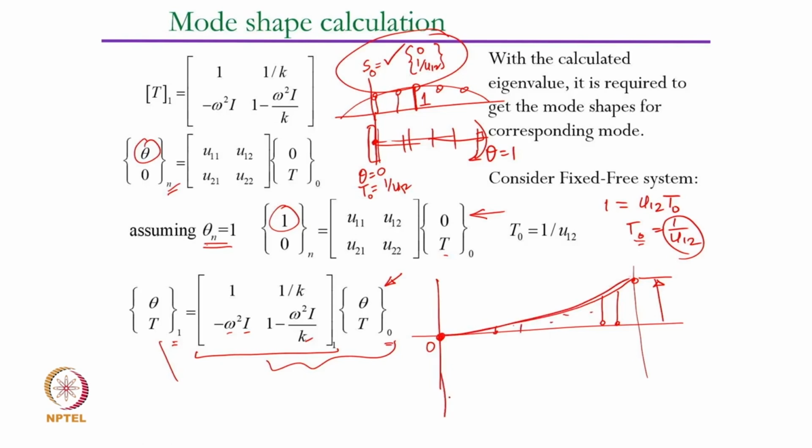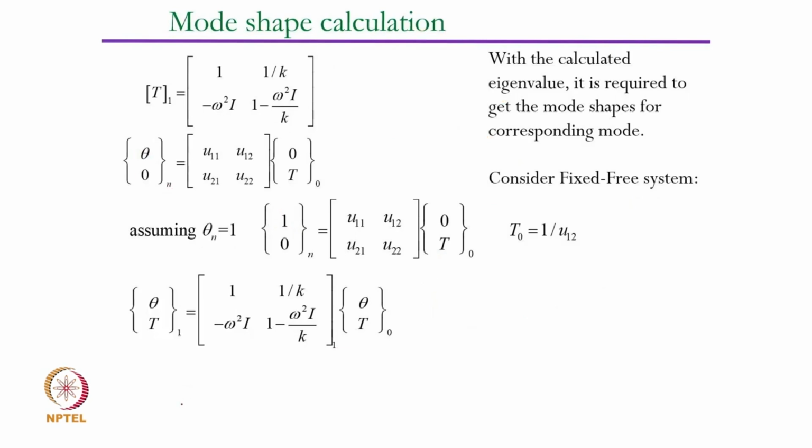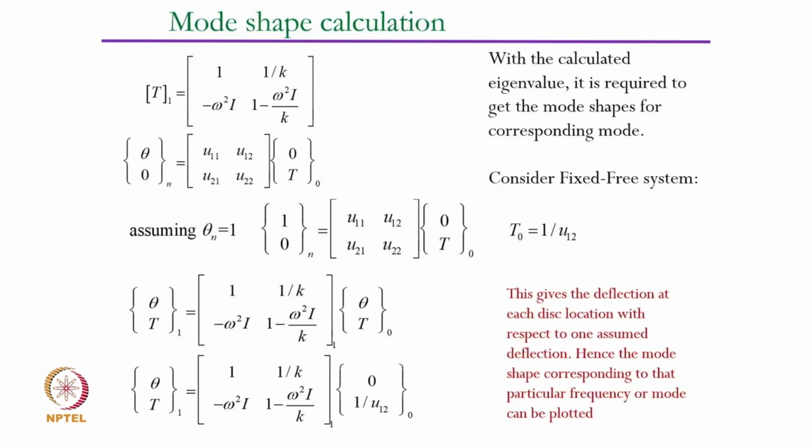You take omega 2, the second omega, and maybe this will be your mode shape, and so on. So, first the root searching method will give you all the eigenvalues. For each eigenvalue, using this process you can find the corresponding eigenvectors, but all of that is a numerical approach, there is no closed-form solution. That basically will give you all the elements of the eigenvector, right. So, this is the way it is to be evaluated.